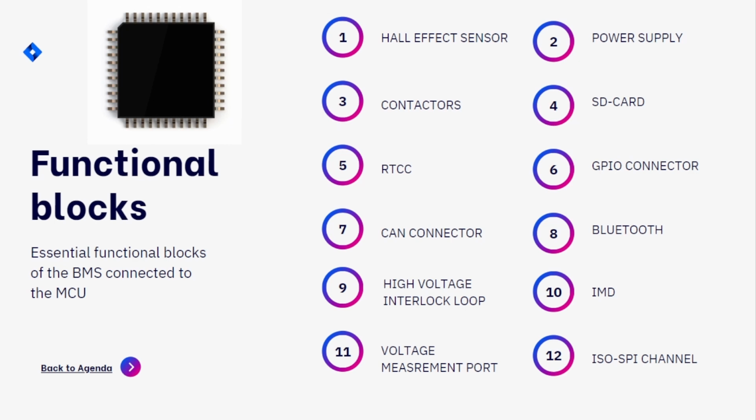So next one is the voltage measurement board. The terminals connected across the contactors are primarily used to check the battery total voltage measurement and voltage based pre-charge. For high voltage and high current applications, there is a chance that the contactor may get welded. In this scenario, the contactor is not allowed to open even if the BMS gives an opening signal. So the BMS identifies that welding has occurred in the contactor and sends an alert message over CAN to external devices for taking emergency action.